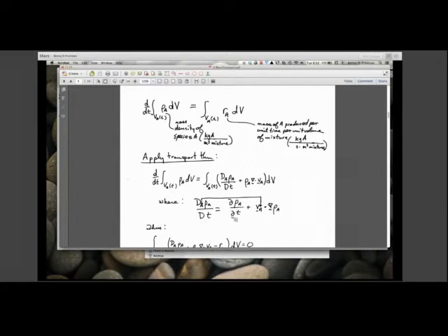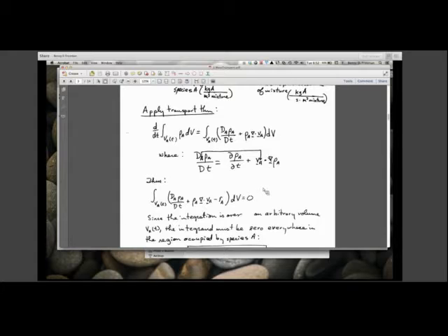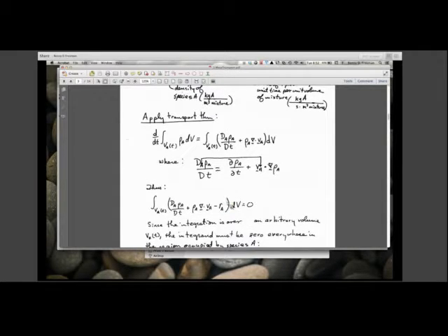We get the so-called substantial derivative of rho A with respect to t plus rho A times the divergence of the velocity of component A. This substantial derivative does have d rho A dt, so if V_A were not a function of time and you took this derivative, you would just get this first term, d rho A dt times dV integrated over V. But because this material volume is a function of time, you have the appearance of these other terms that come about as a result of applying the Leibniz rule, or what we call the transport theorem.